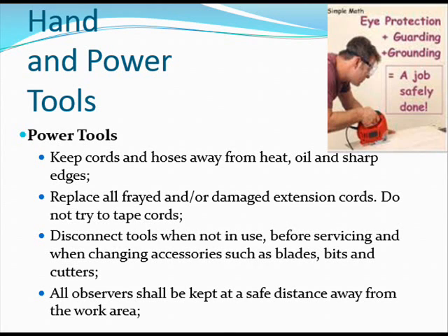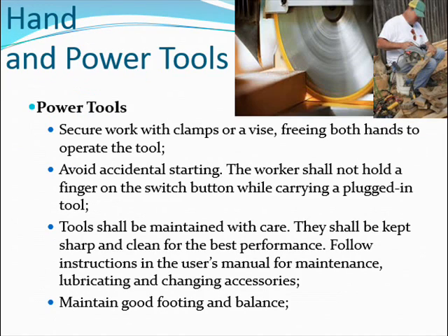Keep cords and hoses away from heat, oil, and sharp edges. Replace all frayed and/or damaged extension cords. Do not try to tape cords. Disconnect tools when not in use, before servicing, and when changing accessories such as blades, bits, and cutters. All observers shall be kept at a safe distance away from the work area. Secure work with clamps or a vise, freeing both hands to operate the tool. Avoid accidental starting. The worker shall not hold a finger on the switch button while carrying a plugged-in tool.